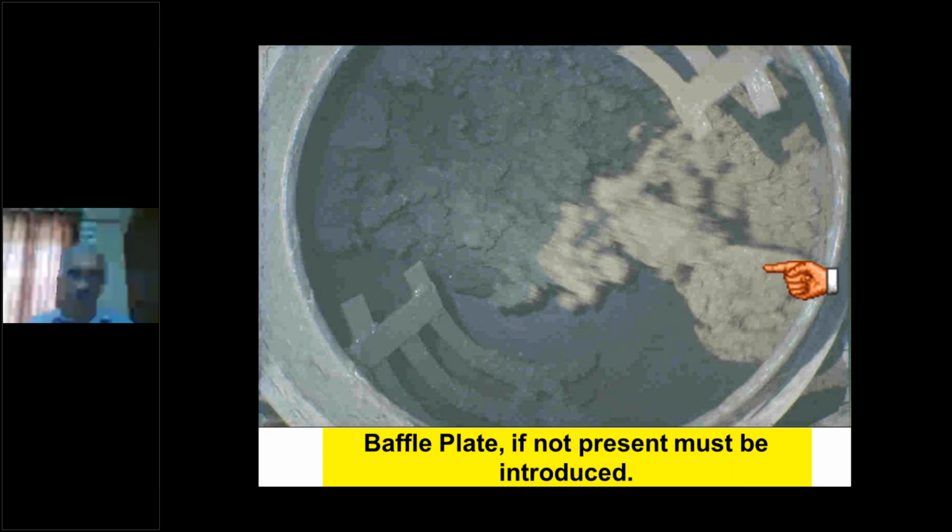Now, bafflingly, the baffle plate has gone missing. The baffle plate has a very good function in mixing. It scoops up the fine material and puts it on the coarse material below, while the blades pick up the coarse material and put it on the fine material. So alternately you feed coarse, fine, coarse on fine, fine on coarse, and therefore you get a proper mixing.